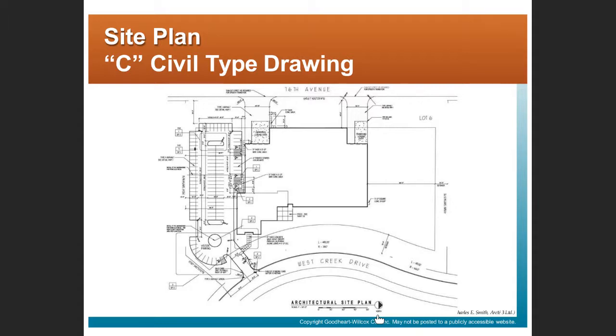Quite often, if the building is not oriented strictly north-south, right, that's easy in a lot of Chicago. We're in a grid in Chicago where everything runs east-west and north-south. But let's say we happen to be in a town where the street grid is not oriented strictly north and south. Then we might have a planned north and a true north, again to help the construction team orient which way the building is meant to face.